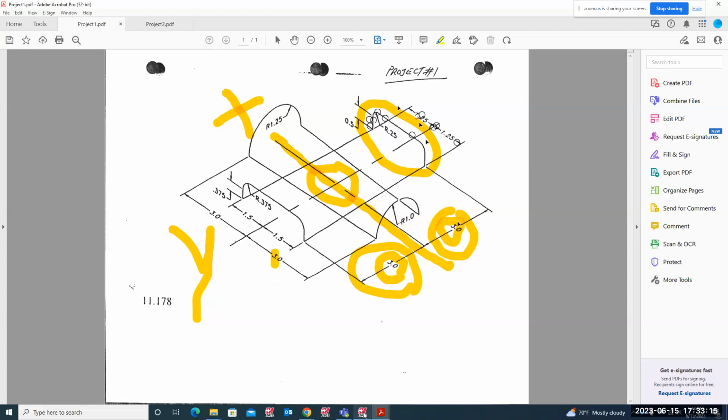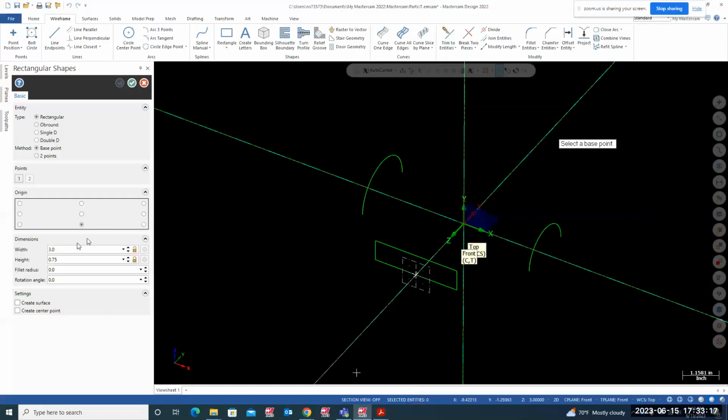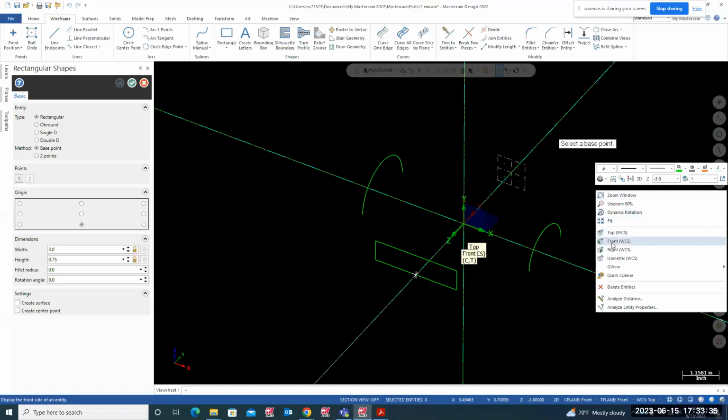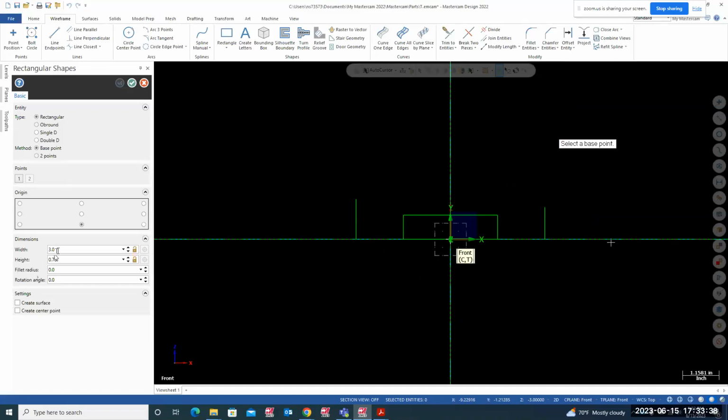So we're going to change your Z to minus, over here. Minus 3 now. Origin is going to shift back over here. Look at that. And now that's where we're going to create the rectangle. So right click, say front, graphic view front, and here is my 2.5 by 750, and that's going to go right over here. Width is 250, that's 750. That's good. And my base point is going to be right at the origin. And there is a rectangle back over here.